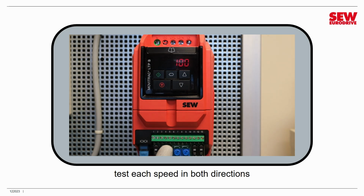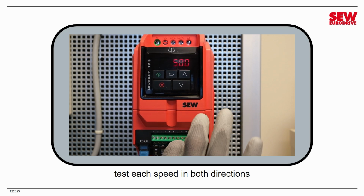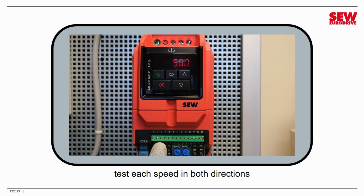Let's go the other direction. You can see that works just fine. Go back to clockwise. Now we'll go to the next set point. We'll turn digital input 3 on. That goes to 250 RPM. We'll check the reverse direction. That's fine. Now we're going to turn the switch off, and we're going to turn digital input 4 on by turning the potentiometer all the way up. As soon as we get up there, it should jump to 500 RPM. It does.